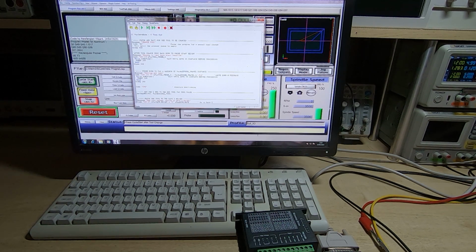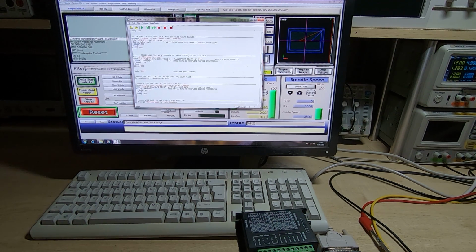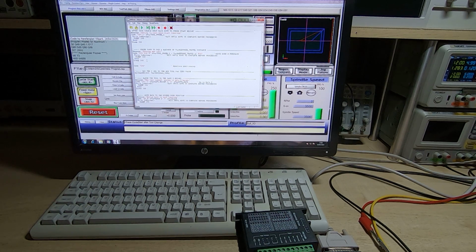It moves rapidly down to just above the touch probe pad. This is the 0 pad, the same pad it used in the first macro. It then slowly moves down till the new tool tip touches that pad, which will be in a different G53 machine location to the previous tool, or most likely it will be unless the tool is exactly the same length. Goes down till it finds the new tool tip.